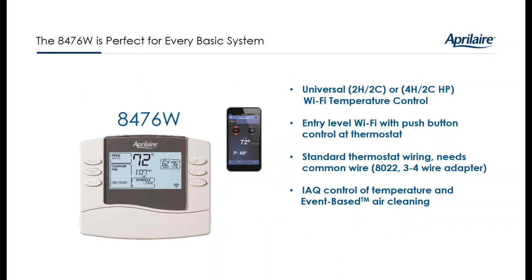Delving into each of the thermostats in more detail, the 8476W: up to 2 heat, 2 cool, or 4 heat, 2 cool with a heat pump. Of course, that's gas or electric. You can wire in an outdoor temperature sensor to give you your high and low balance points. It uses standard thermostat wires, so RWYG, etc. You also need a common wire.